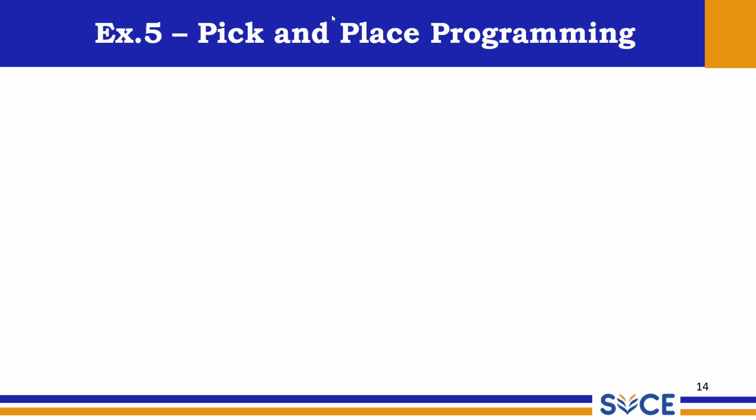So now we'll do the program part. I'll make a very simple sketch here. This is P5 and this is P home, and these are the 4 corners of our palette. We discussed in the earlier slides how to define them. I'm taking this as P1, this as P2, this as P3 and this as P4. Okay. So I'm going to do a palletizing program.